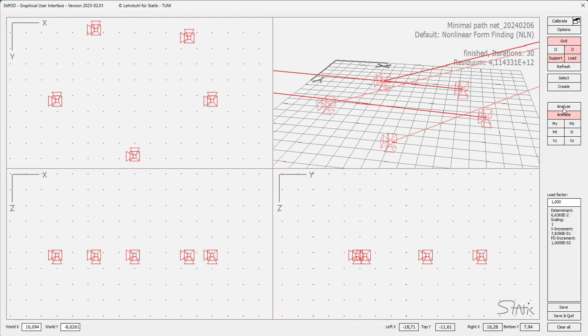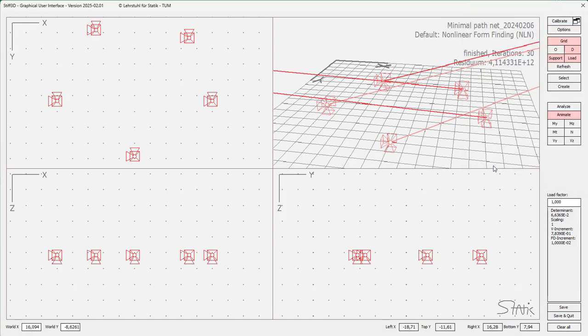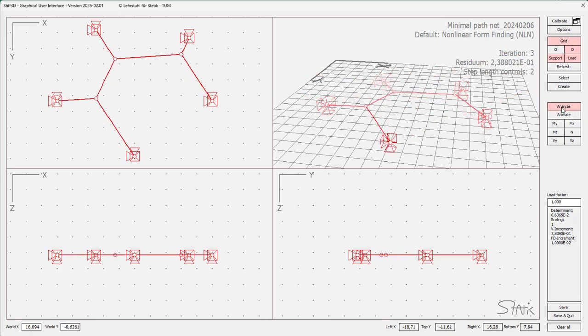The reason is that because of the high nonlinearity, it may overshoot the solution technique. We can damp that a little bit by just prescribing the maximal step length within one iteration. Refer to the previous example that we did, to really damp the Newton-Raphson method a little bit, and we are ready to start again. And you see it nicely converges to the final state in equilibrium.